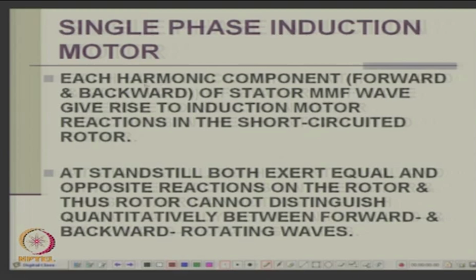Each harmonic component means there is one forward field, one backward field of stator MMF. What will it do? It gives rise to induction motor reaction. There is one forward field. In fact, you are happy in a 3 phase symmetrical machine because there is only one field to deal with in the air gap. Then we make it single phase, we had one more field going in the opposite direction, backward field. Now, I am introducing more fields, with only one winding.